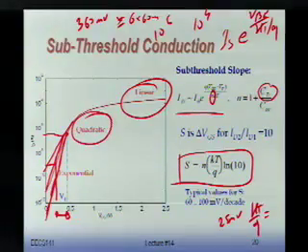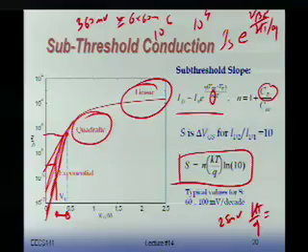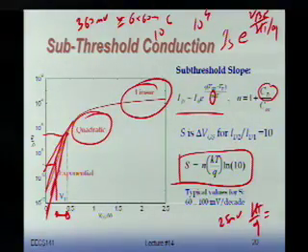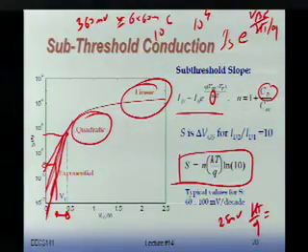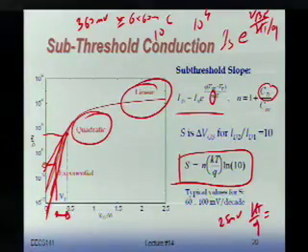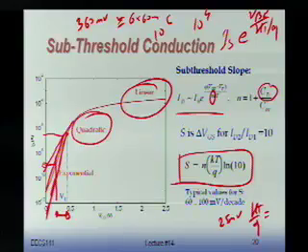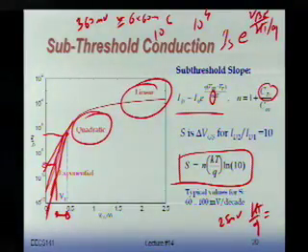But that's a very important observation, right? That this leakage current is going up and up and up. And as a result, you might say, gee, if I look at this thing here, I get 10 to the minus 9th, 1 nanoamp of leakage current. Why do you bother? It doesn't matter. Now, nanoamp, 1 volt, that's 1 nanowatt. Who cares, right? However, if you have 1 billion transistors sitting in parallel, you start multiplying this with 10 to the 9, and you have a watt of power sitting there. And in reality, it can be quite larger than that.